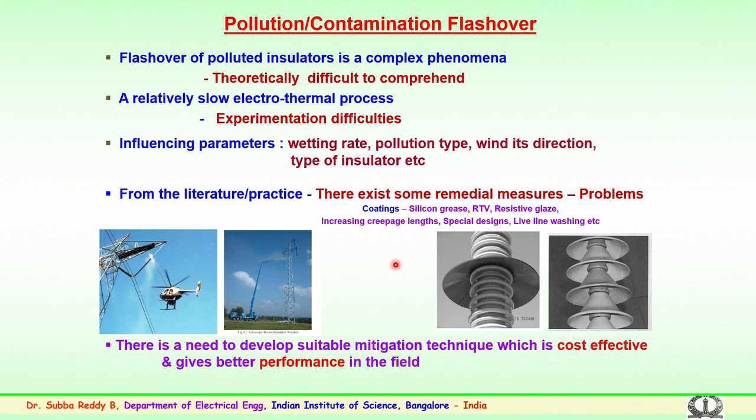So, for this some remedial measures do exist for ceramic or glass type insulators. There are coatings like silicone grease, room temperature vulcanized rubber coatings, and resistive glaze coatings.